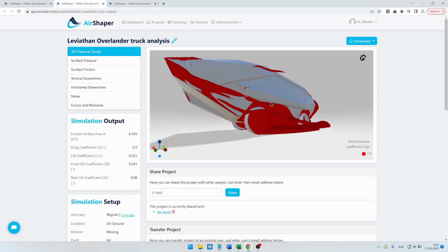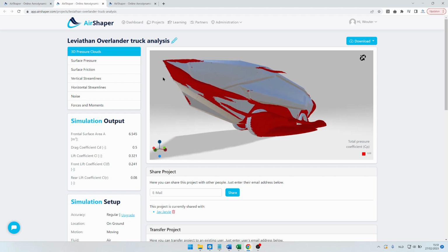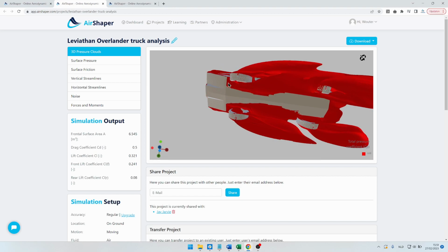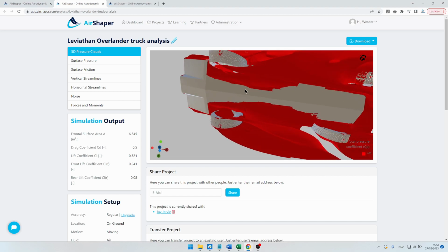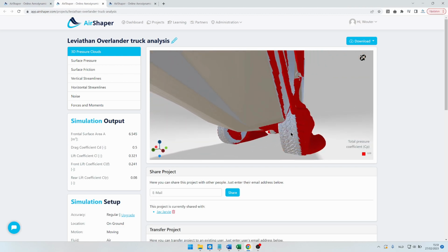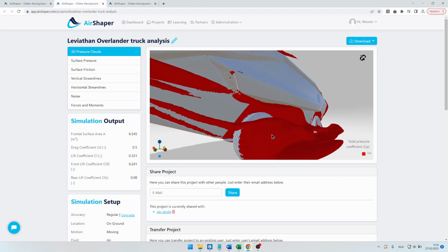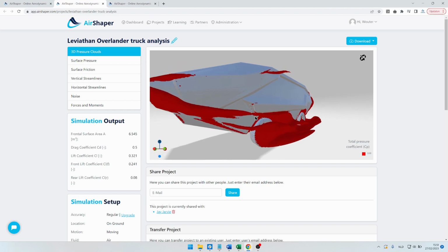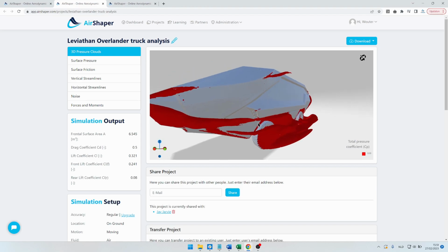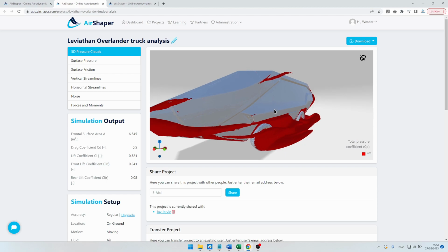Another thing are the wheels. So we see that the airflow stays fairly nicely attached at the bottom here, so it's a nicely inclined surface pushing the air downward. But then at the bottom, wherever you do have open space, like the wheel wells, you will get flow separation. And these massive exposed wheels with a lot of tire threads spinning like a mixer in the air really generate a lot of vorticity, turbulence, drag, and so on. And again, cleaning up these edges where the air again needs to curve around an edge, that would be interesting if it's permitted or possible given the structural frame which is inside.